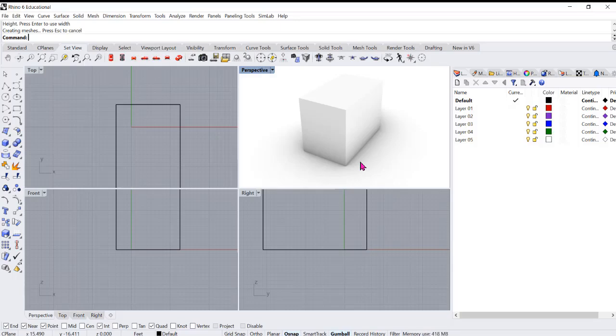So the first thing to do, at least for this exercise, and when you're studying lighting, is be aware that this is on by default, but you can turn it off, and then you can study your rendering with or without the skylight on. Just be aware that when you have the skylight on, that will consume a lot of memory and time from your computer when doing the test renderings. But I'll get more into detail about that.